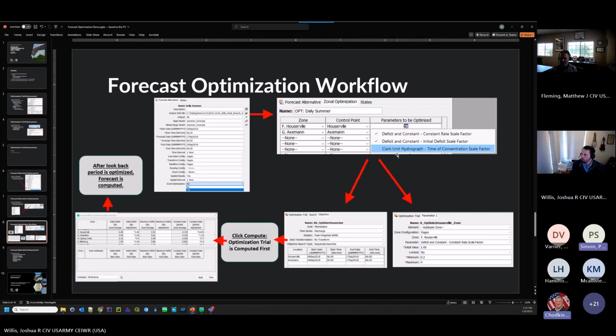Because sometimes I always like to calibrate to pool in the reservoir, because depending on how well you screen your pool elevation data, even if you calculate and try to smooth your hourly inflows, they can be pretty choppy. It'd be a lot better if you could just try to hit your pool elevation. Okay. Awesome. Thanks for bringing that up. I'll make a note to look into stage.